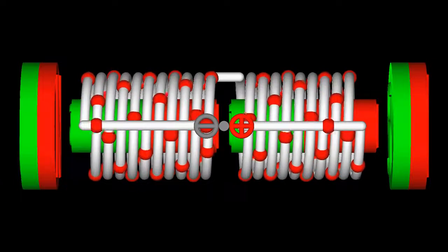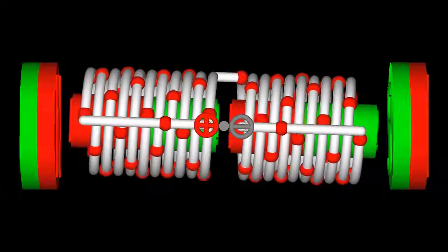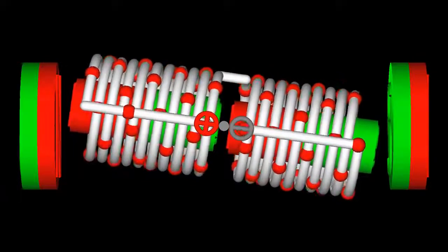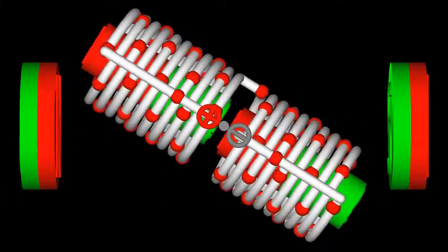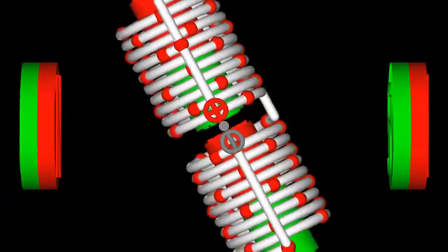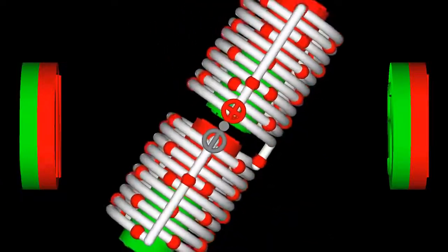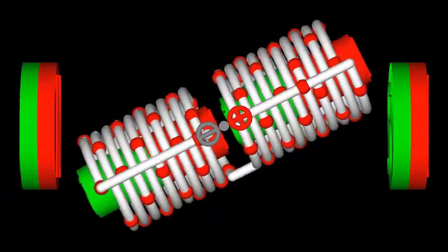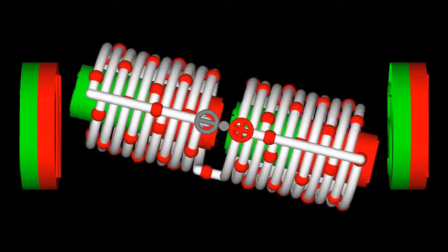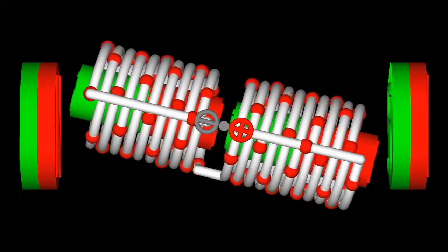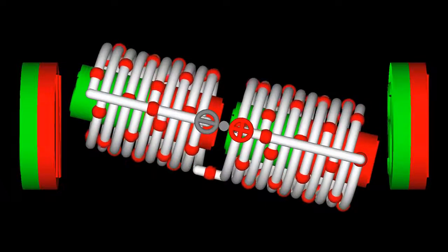To make the electromagnet spin again, the polarity at the solenoid has to be swapped. If the electromagnet is turned clockwise for some degrees by hand, it will spin clockwise for another 180 degrees if it is released. If the polarity is swapped again at the highest point of overshooting, we get a continuous rotation.